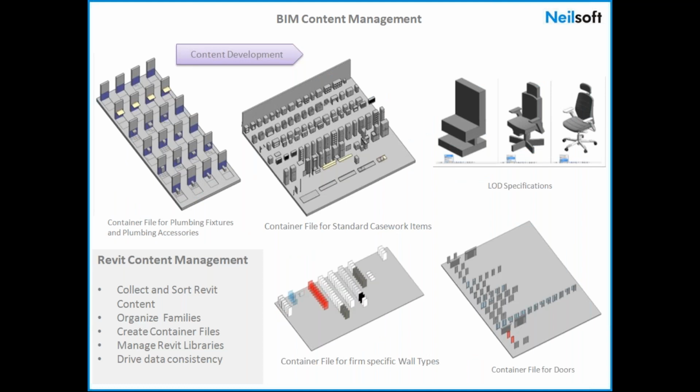As part of the content development, as we are developing the families, content management also becomes a very crucial area where, with multiple people working on the model, we want to maintain a standard of what families are being used and how people are using them, what parameters are being updated, how families are being created, what kind of LOD specifications are being used, at what stage, and what type of LOD is being used.